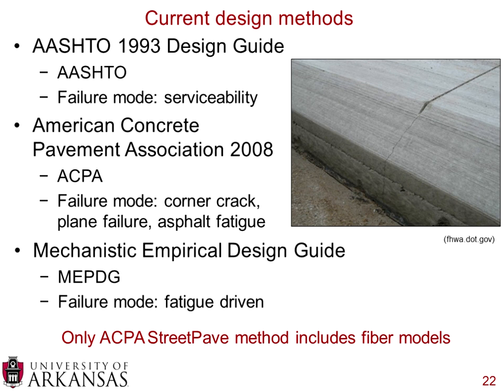And when you're thinking about how we're actually going to design this pavement structure, the National Concrete Pavement Technology Center recommends one of three methods of designing your new roadway. You can use the AASHTO 1993 design guide, and for the rest of the presentation, I will simply call that the AASHTO method. An important note here is that the failure mode you look at in the AASHTO design guide is serviceability. So what is your serviceability rating? That's what drives your failure.